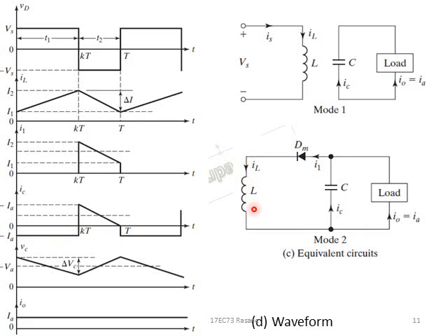The current through the inductor will continue to be positive in this direction, and this current flowing through the capacitor and D1 will be the same current, and we will have the current flowing through the inductor in this fashion. The capacitor also will carry that current, and the current through the load, we are assuming, is the same, always DC and fixed.